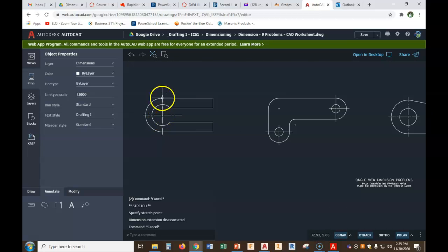Now what do we do with a fully rounded end? This is fully rounded, okay? So this is a radius. Think about this. This started life as a hole. Okay, so there was a hole in this thing. So we had to use a drill bit. So we need diameter for that. I know there's a slot cut over to it, but we got to use diameter for that, okay? So let's do that real quick.